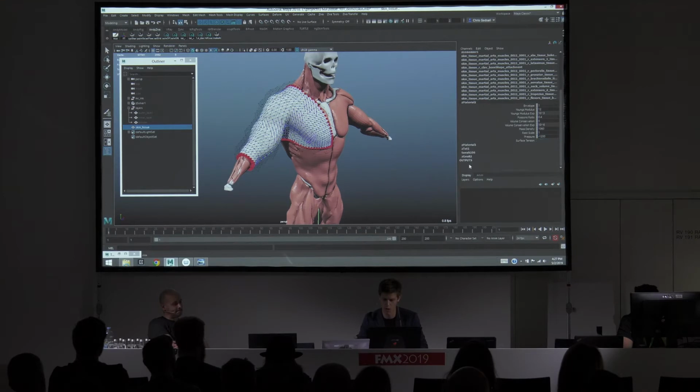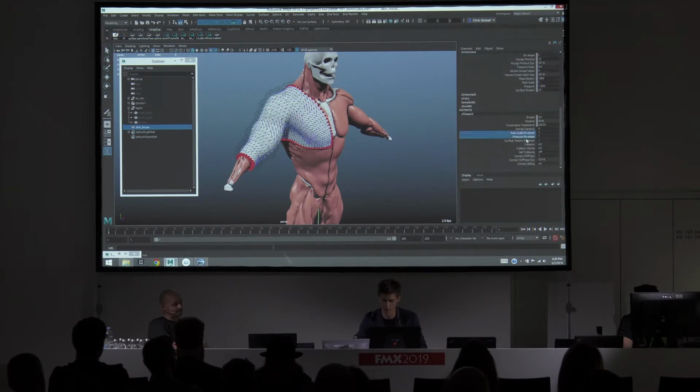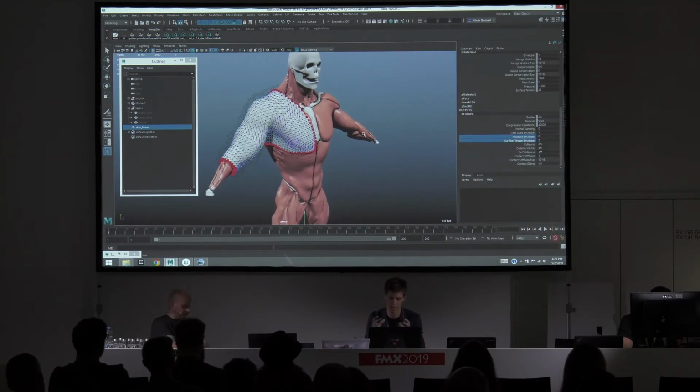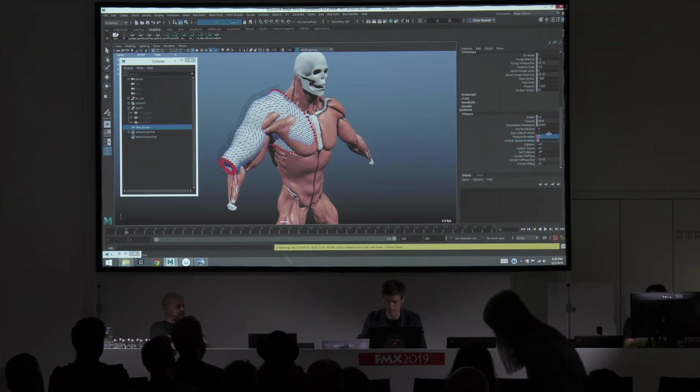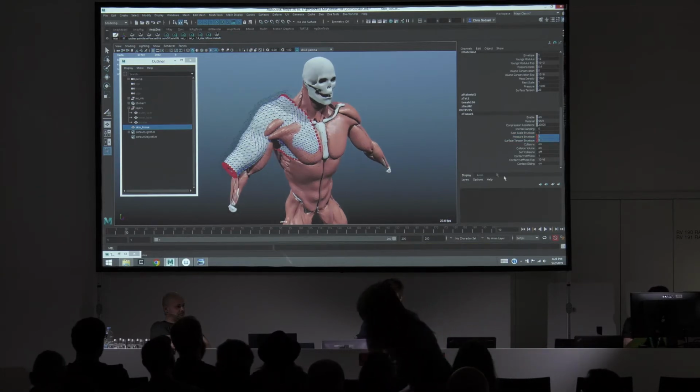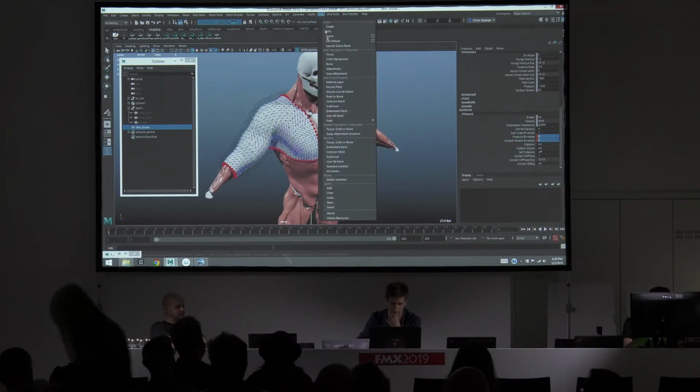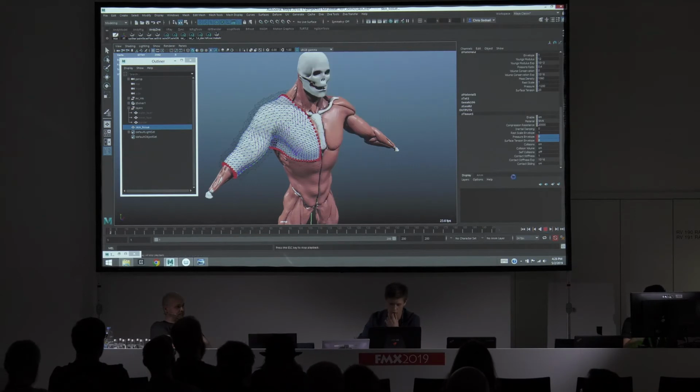And we want to ramp those attributes on over time. So we can do that here. Because if you have it just jump on the first frame, it's going to be too fast for the solver to catch, so it'll jump through the underlying stuff, and you'll miss some collisions. Do 10 frames there. Cool.